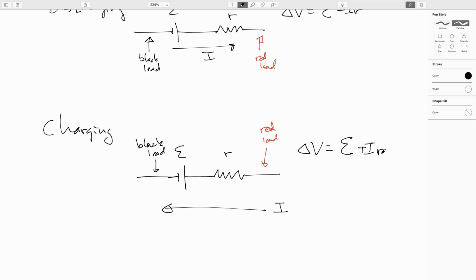So about the word charging, this is where a lot of sources of misconceptions about batteries come about. As we've already seen, all batteries do is just move electric charges from one side to the other. The actual net electric charge in the battery is 0. You have just as many positive as negative ions at all times. That never changes. We just move them around in order to keep shoving charges around a circuit.